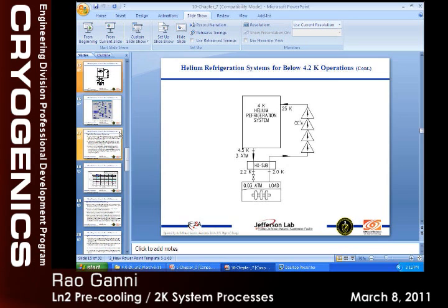All of a sudden, for example, you are bringing one warm cryo module from 4K to 2K, we call it pump down, and we are trying to bring that online. So we are trying to process the pressure from 1 atmosphere down. What we are doing in the process is increasing the flow through this higher, although we are not supplying any more because it's already full of liquid. We want to get the pressure down. We have an unbalance here. So this temperature will keep dropping because there's more refrigeration than the high side to cool it. So it will start processing more.